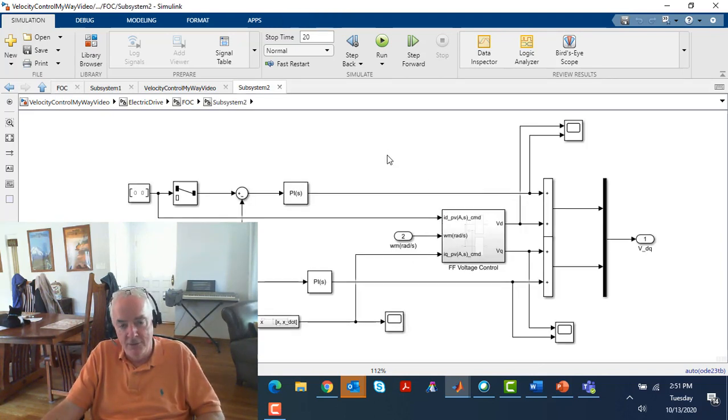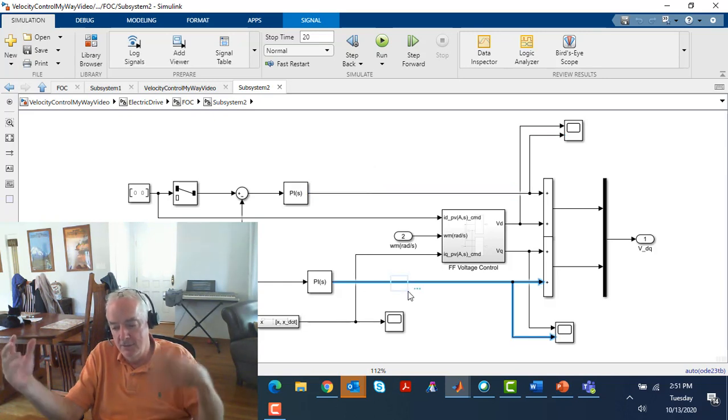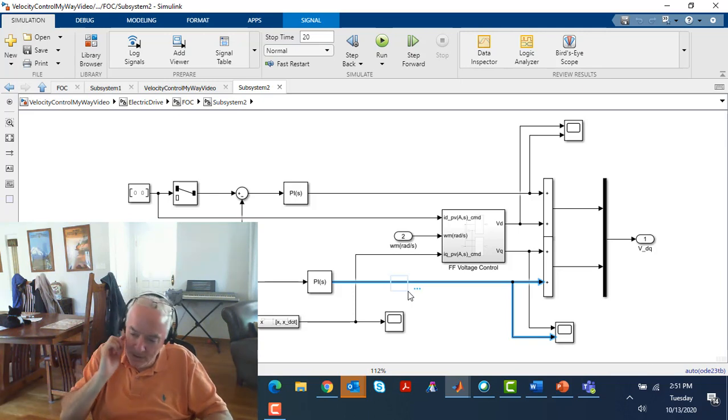It simplifies the math tremendously, and it puts us in the natural space for developing the controls for an electric motor. Then it really comes down to let's get the right direct current, let's get the right quadrature current, right? And these two things essentially will set the magnetic fields and therefore the torque that we're going to get out of the motor.